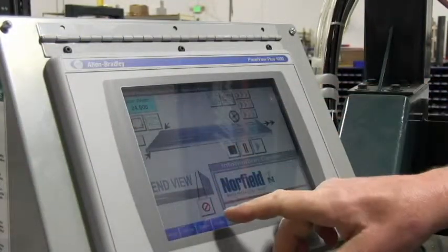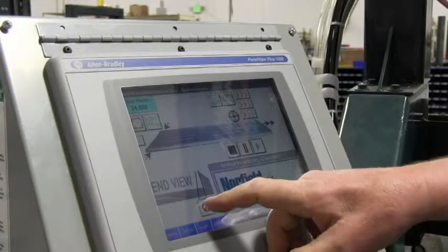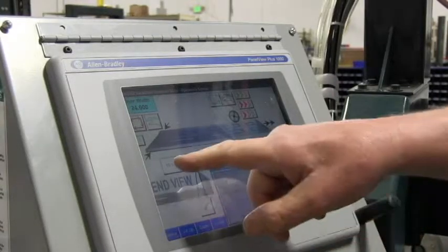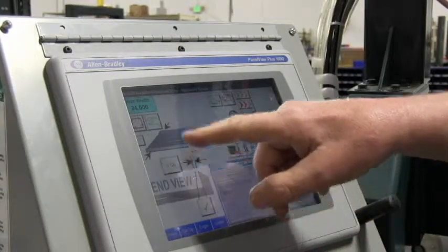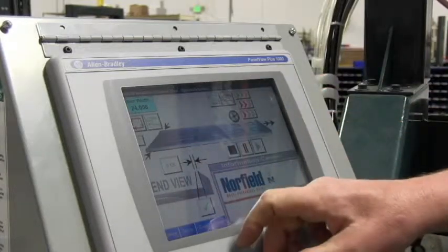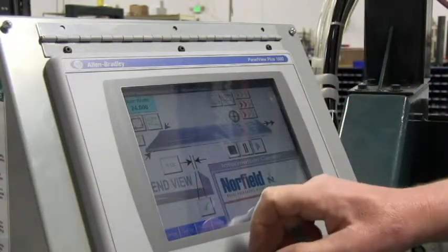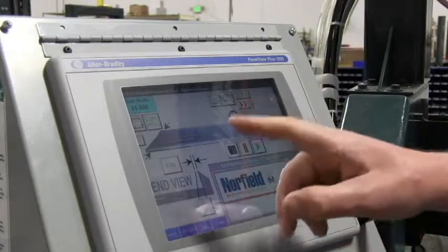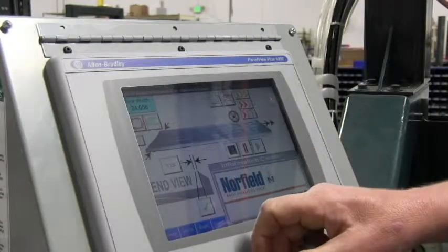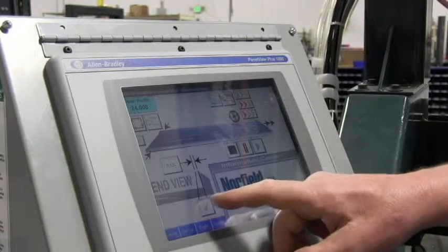It calls for 24 inches. We start the sizer. We're looking for 1/8 of an inch under, so we'll expect the door when it comes out to measure 23 7/8. If that does not measure 23 7/8, then we'll need to calibrate the sizer.